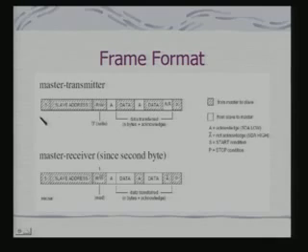So, the complete frame format is, you have got the start transition, you have got the slave address, then you have got the read write bit, okay. Then actually you start the address. Now, here A is the acknowledgement which comes from the slave. So, after your first byte which indicates address, you have to have an acknowledgement from the selected slave. If no such slave exists or is currently connected to the bus, then obviously the acknowledgement will not come and the frame has to be aborted.